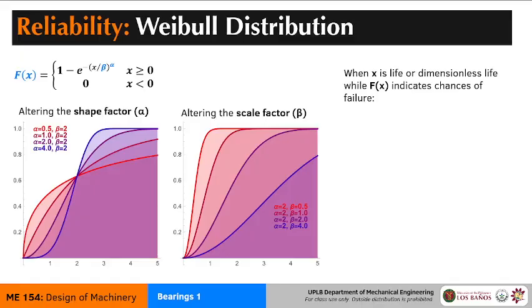If your beta is really low, less than 1, it's probable that the cause of death for your units or components is inherent in the design. So you may have to go back to the drawing board and rework some part of your component in order to make it sturdier. Otherwise, it's just going to keep failing constantly, and you will lose the trust of your customers.